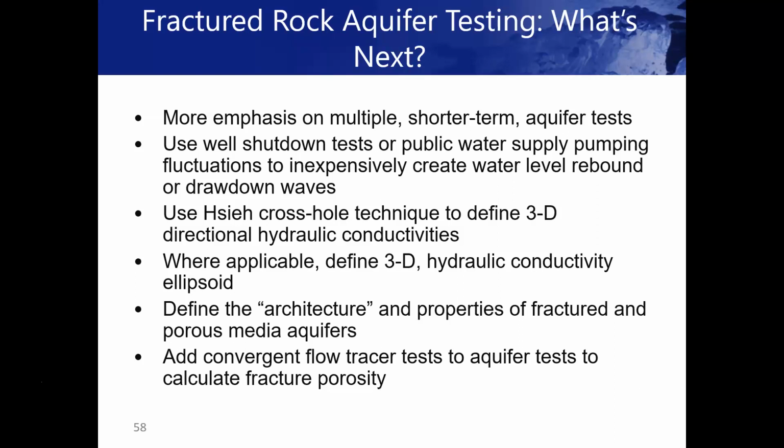But if you pump it at a higher rate, if that's possible, you can eliminate that problem fairly quickly. But that is a factor that you need to take into account, especially if it's a large diameter well. Like I've seen wells that were 3 feet in diameter. You pump a well, let's say a 3-foot diameter well that's 30 feet deep, there's a lot of water in there. And if you're only pumping at 1 gallon a minute, let's say, because you think that's the sustained pumping rate of that well, it's going to take a long time to pump all that standing water out of the well. So you need to take that into account when you analyze the data.